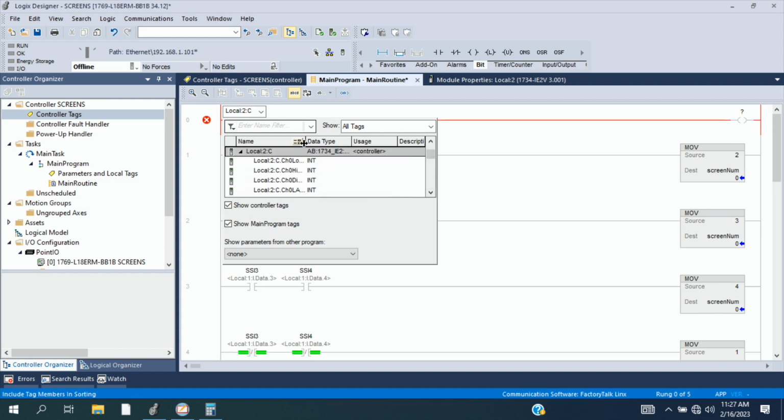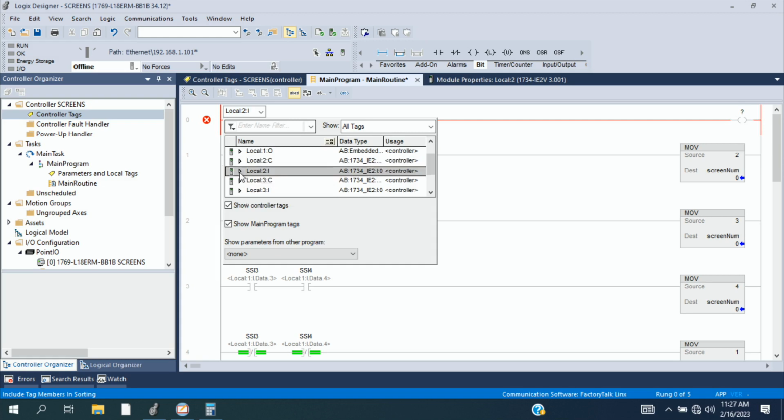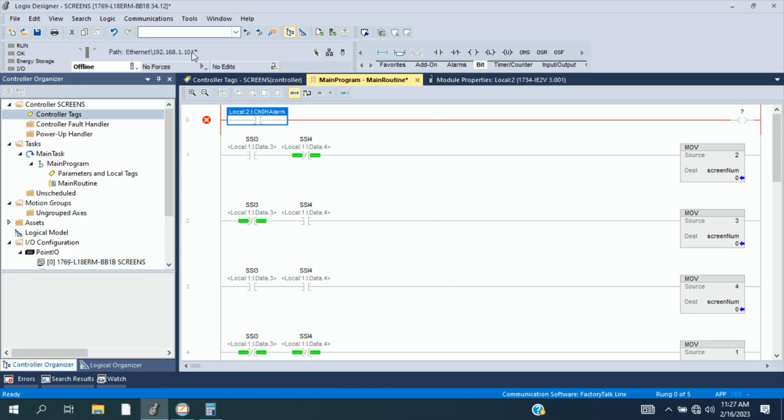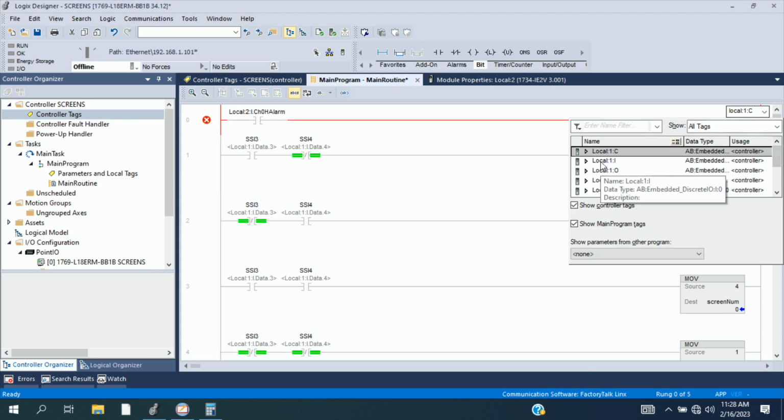Sometimes you've got to find these buggers, right? So those are the alarm limits. I think I'm on the wrong side of things here. So I want to find the channel 2 input stuff. Okay. So let's say that we were to reach the high alarm for channel 0. That's this one, channel 0 high alarm. I can use that bit to trigger different things, and I need to take a peek at some of my outputs, but I think the green light is output number 0. I don't have the template on here, so let's go to the local inputs and just grab something real quick here.